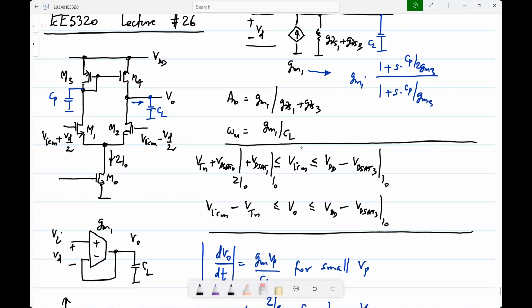A common mode limit to which one? Again, we will not be using the op-amp in open loop, right? We'll use it in closed loop, and we apply some signals. And those signals may cause some common mode input for the op-amp and some differential input for the op-amp. Yes, it is possible that with that, maybe with some combination of parameters, you reach the triode limit before this. That is possible.